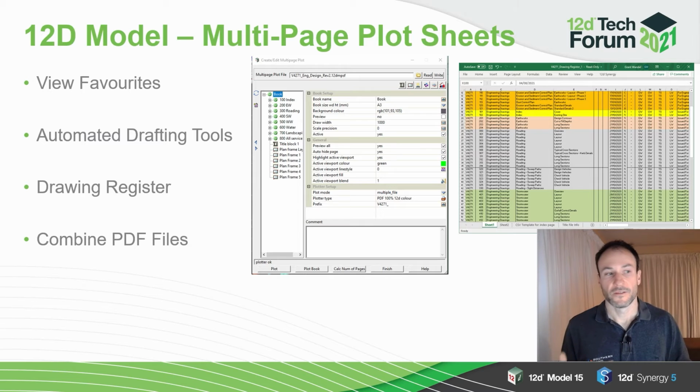So the multi-page plot sheet having the ability to plot by chapter or plot by individual page, instead of having to go through the whole sheet and spit them all out, can take a bit of time. So if you've got one little error, especially in those final little checkings where you've gone, oh, I just need to fix that one thing on that sheet, you can just plot that sheet out and then combine your PDFs together using combine PDF files.